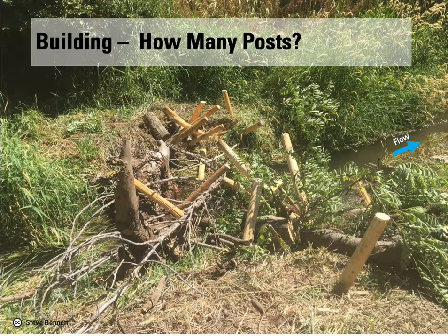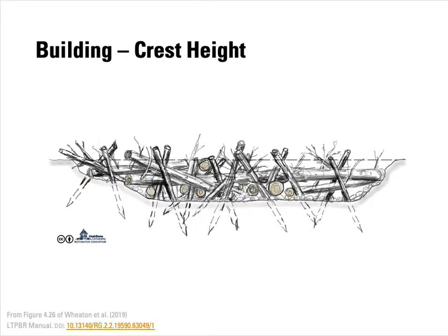Many times people ask, well, how many posts and where should we put them? The answer is wherever you can get the posts to go into the bed firmly, and as many posts as you need. This will just come from experience, and if you're not sure, maybe put more posts in, and as you work at the site and experience high flows, you might learn that you need fewer posts and you can start using less.